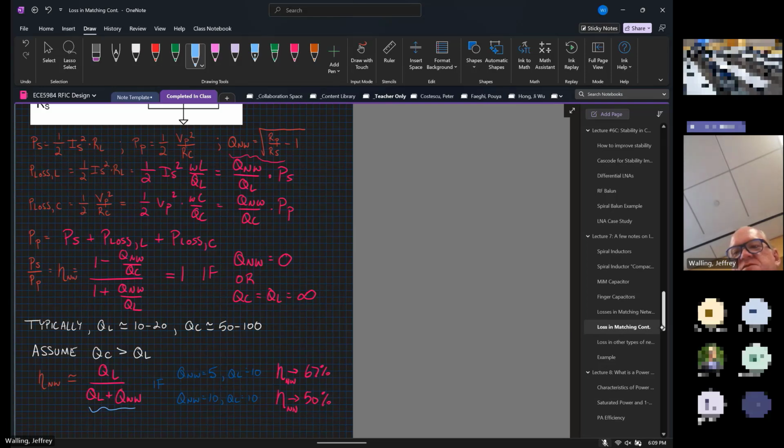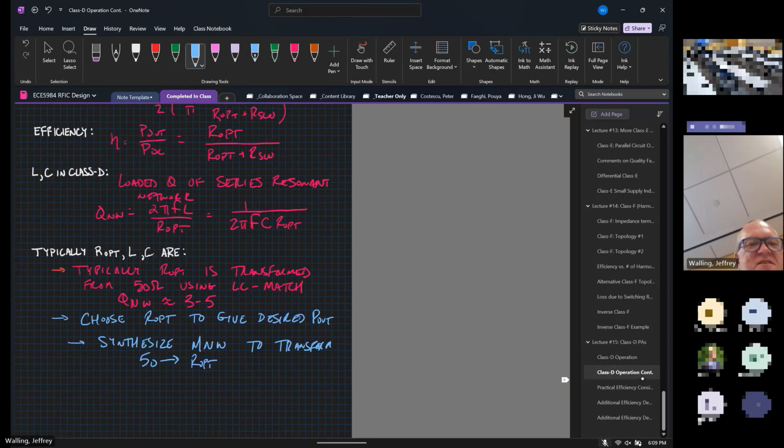Now, if you've been searching through this 22 nanometer kit, one other thing that you might have noticed is that the quality factor of the inductors, 20, is very optimistic. If you were searching for anything in the nanohenry ballpark, the Q is probably closer to 10 to 12. Yeah. You can find inductors that have Qs in the 20 ballpark, but those are hundreds of picohenries.